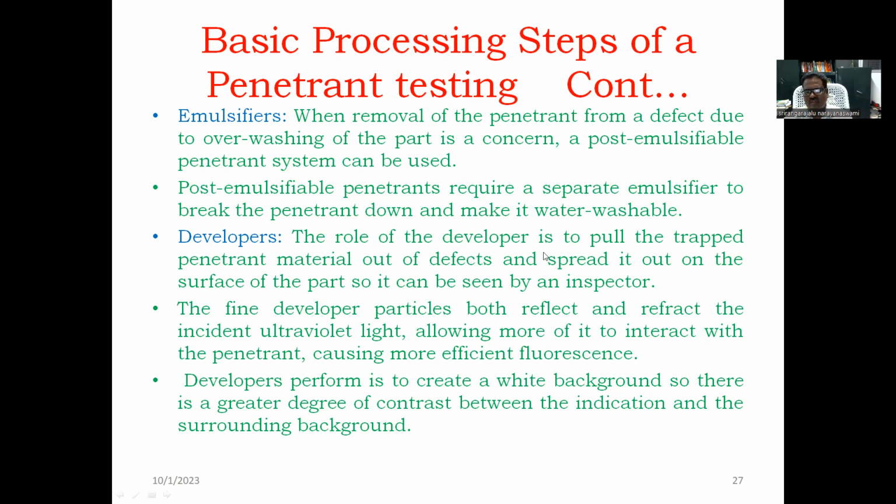Developers: the role of a developer is to pull the trapped penetrant material out of the defects and spread it out on the surface of the part so it can be seen by an inspector. The fine developer particles both reflect and refract the incident ultraviolet light, allowing more of it to interact with the penetrant, causing more efficient fluorescence. The developer's purpose is also to create a white background, so there is a greater degree of contrast between the indication and the surrounding background.